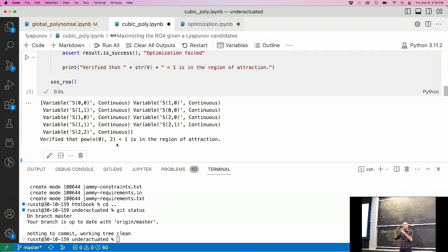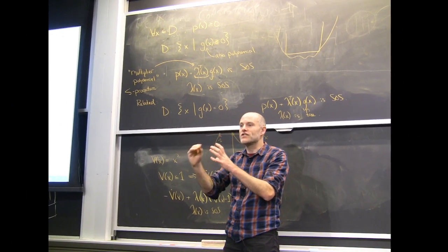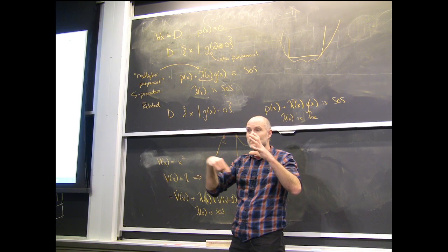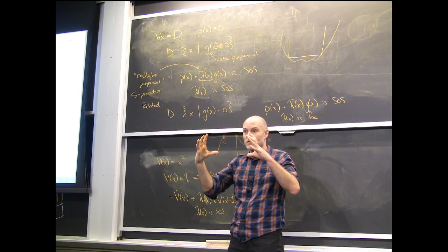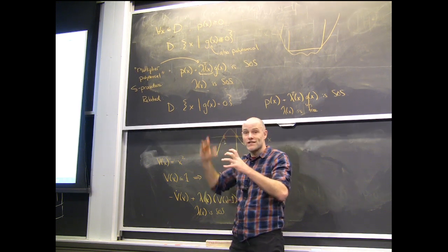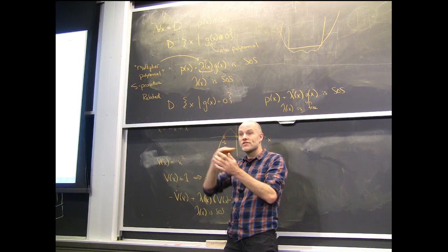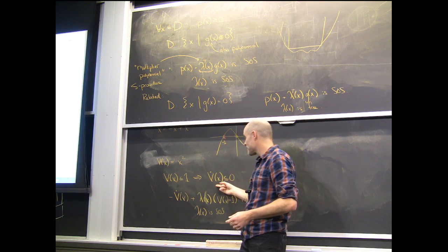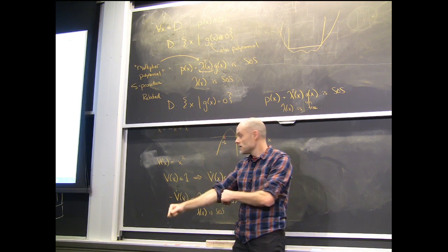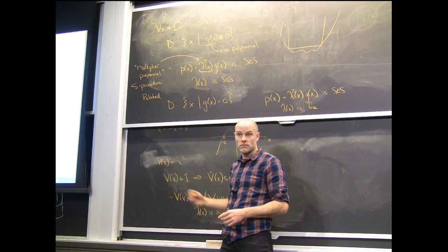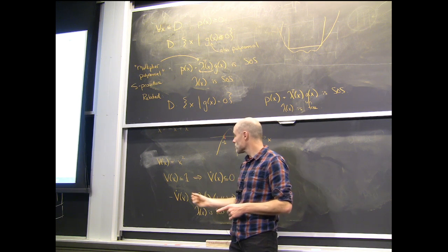Remember, the conditions for a region of attraction are that you have to be an invariant set in addition to being a region. So if I certified over some region in space that V dot was negative, that would not say it's a region of attraction yet. I also have to show that that set is an invariant set. So the choices of domains for region of attraction are almost always sub-level sets of V, because then they're self-consistent. Once I'm inside V and I've certified the conditions inside the V, I won't leave V. So that means this region's also an invariant set, and I get both of them for the same price. Okay?